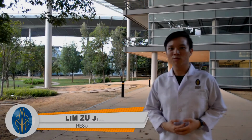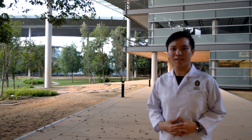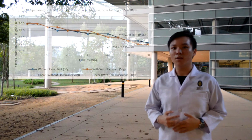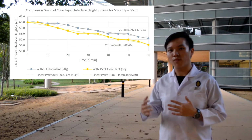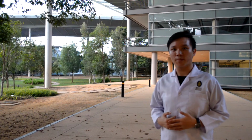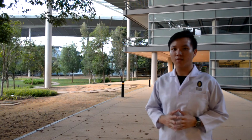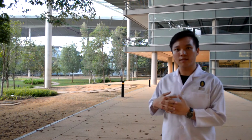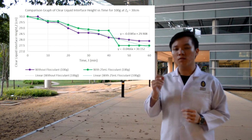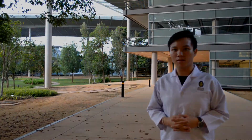In experiment 2, the effect of different volume of flocculants on the settling rate is being studied. The graph of clear liquid interface height versus time shows a decreasing trend for both 50 gram and 100 gram. At the same time, the graph of clear liquid interface height versus time for Z0 equals 90 cm and 60 cm with different volume of flocculant is showing a decreasing trend as well.